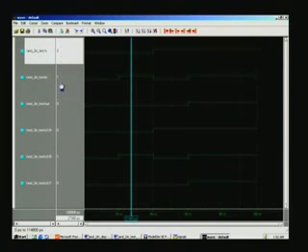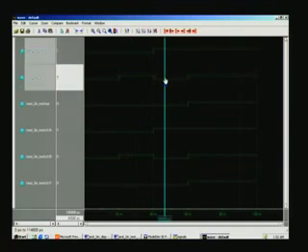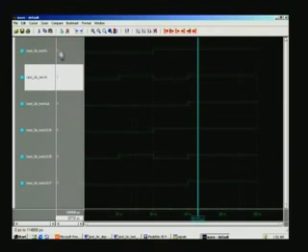If you AND these two, you should still get 0, that is what is here, and it shows 0 here. And similarly for the next, at 40 nanoseconds, we are again changing here. So that is now 1 and 0 applied. The stimulus applied is 1 and 0 for A and B. And that's what you have, high here and low here. And for this, naturally, you have to have 0 again, right? And the last one is 1, 1. This corresponds to 1, 1 here, and the corresponding output must be 1 here. That's what you see here.